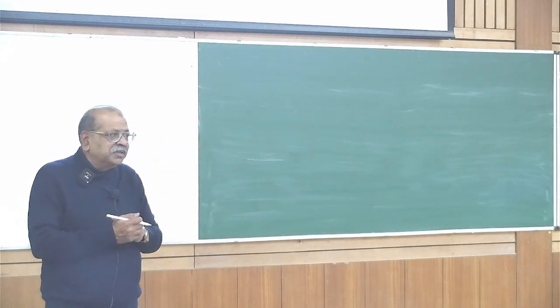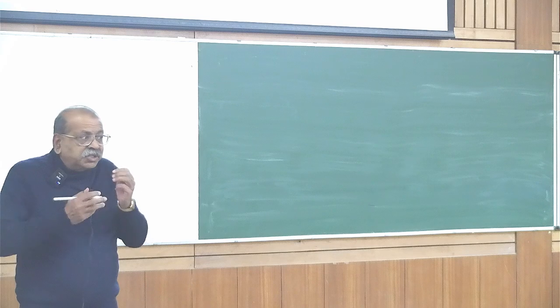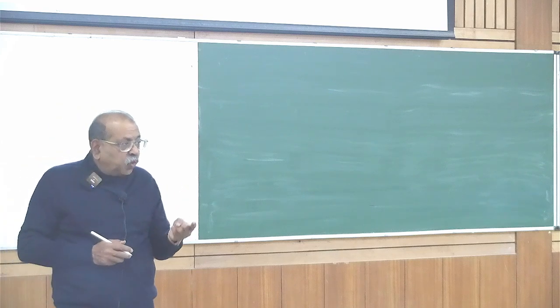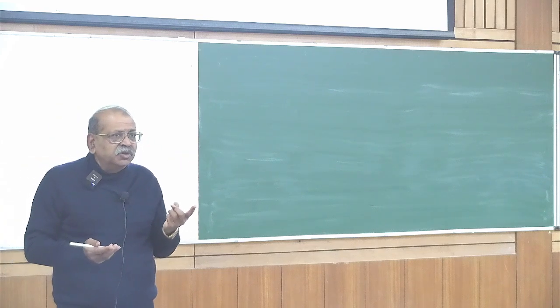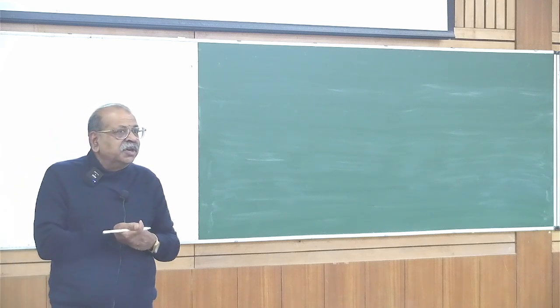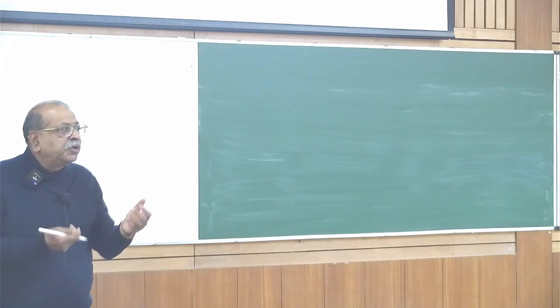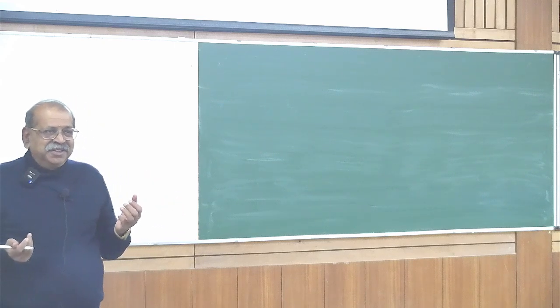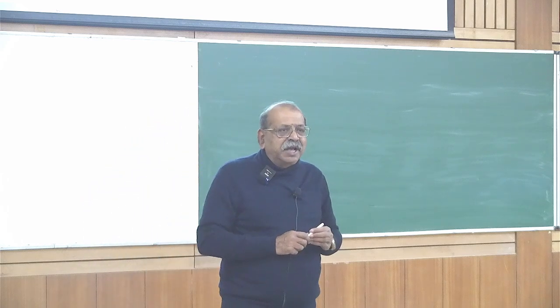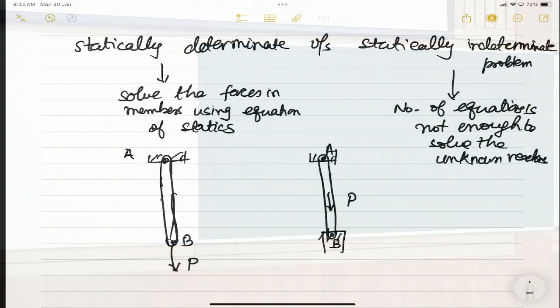material properties. So in the statically indeterminate problems, we need three things. One, equation of statics. Two, the geometric compatibility equations, and three, the force deformation equations. And these three principles we will be using throughout in the solid mechanics course. So let's write these down.